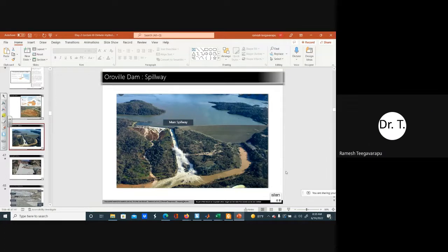Oh, yes. We need a lot of dams in developing countries for controlling the spatial and temporal variability of water, irrigation, water use, water supply, and everything. But the problem is that we cannot build large dams these days because of environmental concerns and inundation upstream. So large dams cannot be constructed. But when you construct small dams, which are okay with environmentalists, the problem is that small dams cannot have enough storage. So there are mechanisms by which you can try to improve the operations so that you can sustain the water.